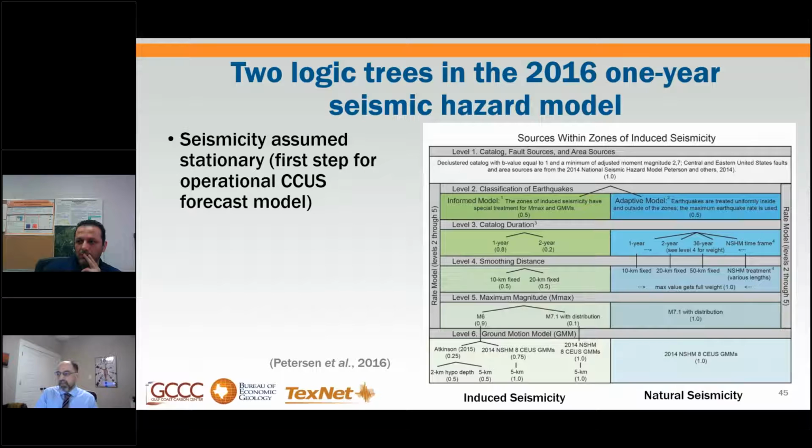I would say that for some cases, you should go to magnitude 5, especially when you are close to urban environments. Magnitude 5 earthquakes will certainly create some problems in areas where the distance between the urban environment and the seismicity is very small, like 10-20 kilometers. And of course, it depends also on the type of buildings and if they have been built based on any seismic code.